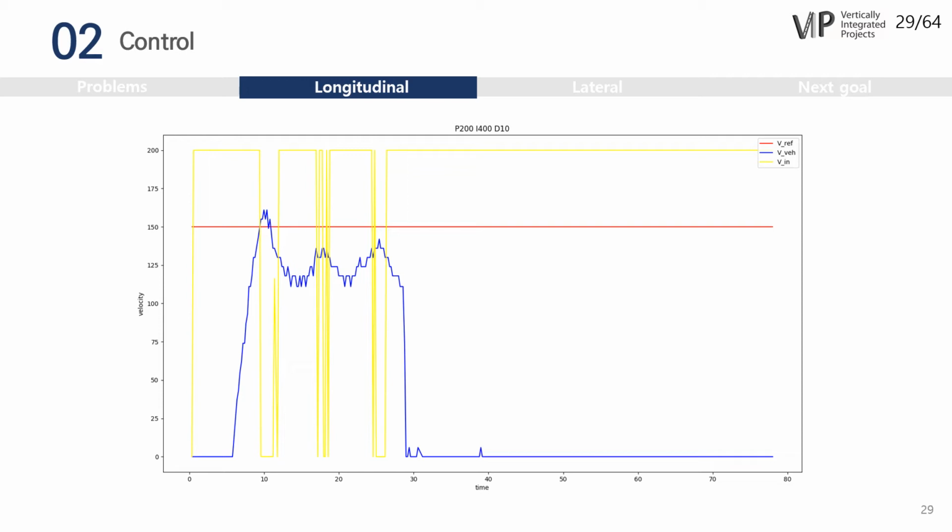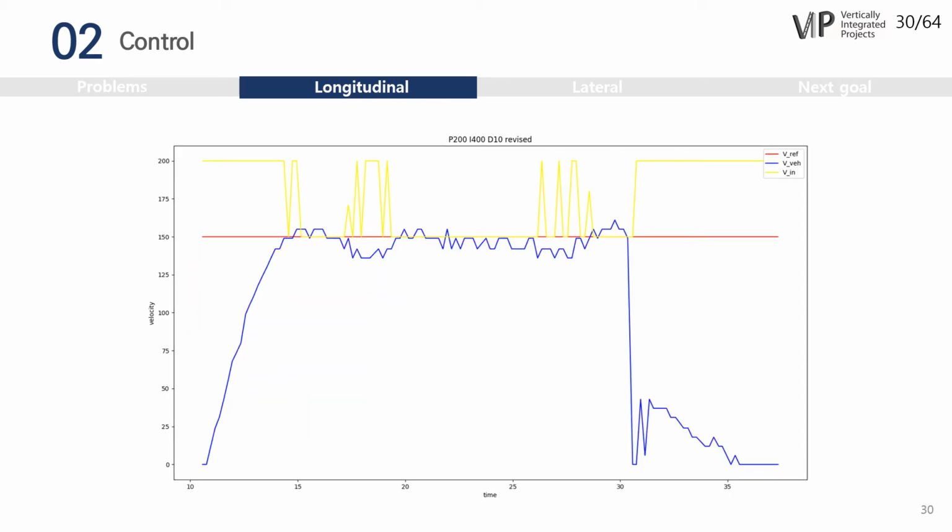Different from the general case, we gave the speed to the vehicle directly, not adjusting the power of the motor. So no matter how large a P value we put in, once overshoot occurred, we couldn't help putting a 0 or minus value for input. This looks very simple, but we haven't done this before, so we couldn't realize it right away. By doing this, we learned one lesson. When it comes to control, figuring out how the system behaves is always the first order.